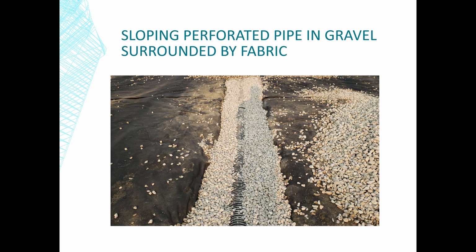So once they start burying the permanent pipe, because it was at different elevations, the farther to the one side of the building this pipe has to get higher. It means that the water table isn't really getting lowered evenly in all locations because the pipe is sloping.